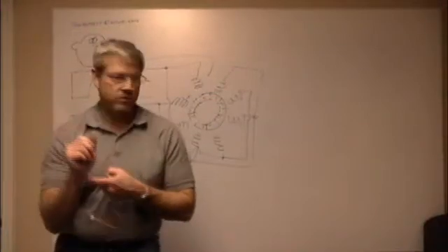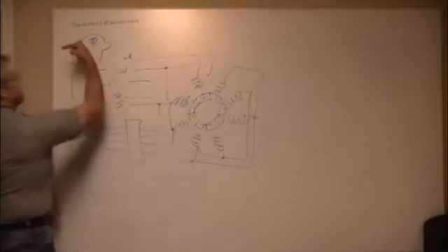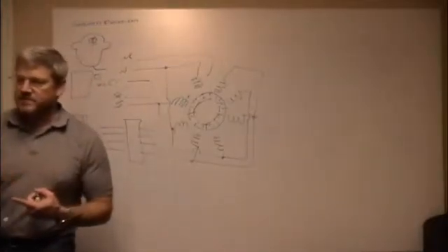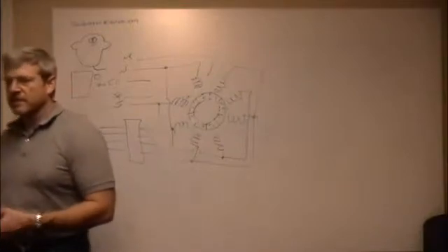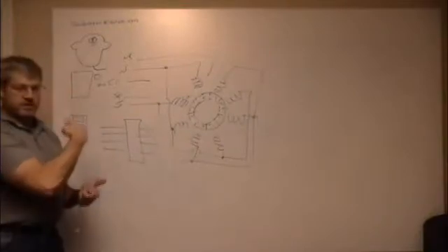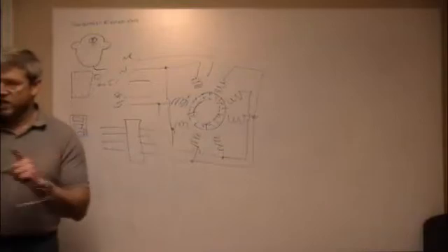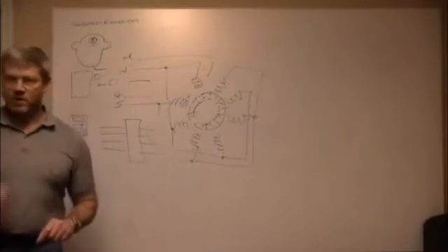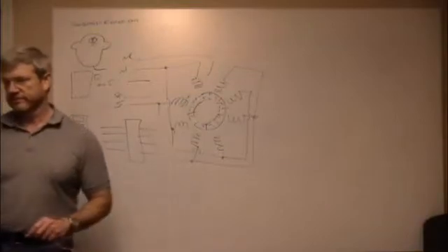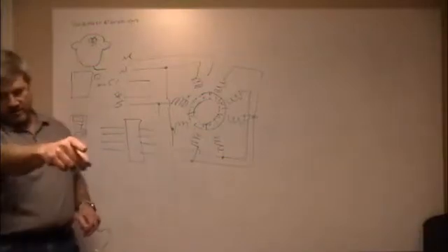So if I want to go from here to here with a stepper motor, I've got to go step, step, step, step, step, and so on. If I want to go from here to here with a servo, I change that PWM one time to what I want, and it'll bam, and it'll go there. And that's the servo. And that's that one right there.